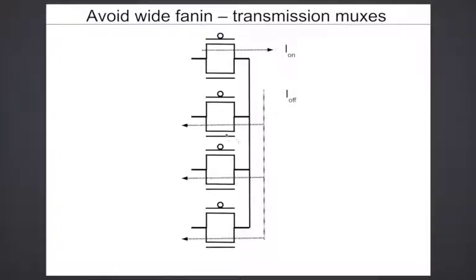See, the reason this is a nice mux to use, if possible, is that NMOS and PMOS both are in parallel, right? So both help each other. So the speed is much better if I use this mux. Whereas if I use a tri-state inverter, what is a tri-state inverter? Imagine this mux, there is one simple inverter driving this. The other way of doing the mux is to push this PMOS and put it in series with the PMOS of the inverter, and put the NMOS in series with the NMOS of the inverter. So you have a series PMOS and series NMOS. There, the speed will be lower than this, right? Because in a pull-up, only one PMOS of the mux is coming in, and in pull-down only one NMOS. Here, in this structure, both are there in parallel. So that's why you would prefer this.